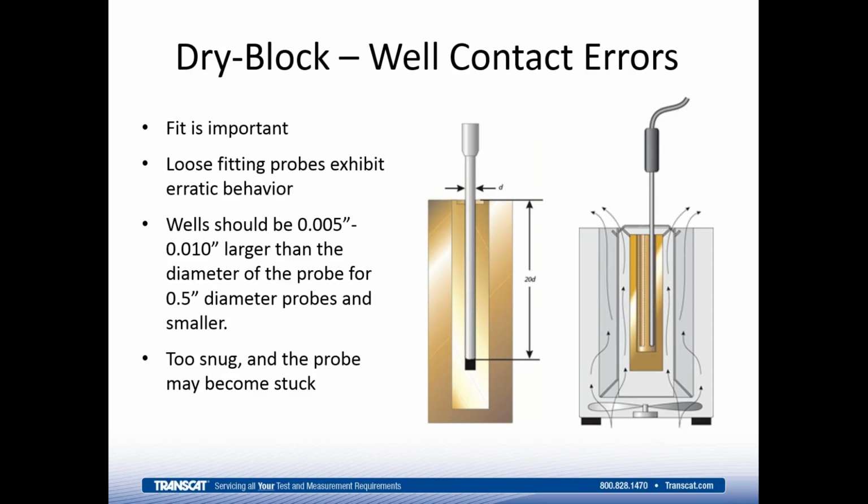I've seen guys who got their probe stuck inside of the insert, and they grab the probe with two hands, put one foot on the dry block and yank real hard, and that damages the probe. It'll get bent. When I worked in the lab, you could always tell who'd done that. There's some telltale scratches, some bends. You'll never be able to fit it in a dry block again, that kind of thing. But if you've got a probe that you can't fit into a dry block, we'll talk about what to do about that later.